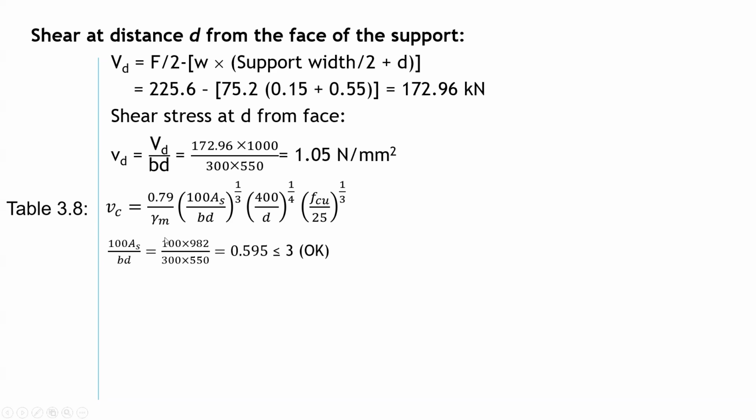In this case, for that beam, we have 2 bars only at the critical section, 2 bars of diameter 25. So the area will be 2 times 491, which will give us 982. So this value here is equivalent to 2 bars of diameter 25 millimeters, because we have 2 bars extended to the end or to the shear section, and 2 bars were shorter, so we only take the area of the tension steel bars at the shear critical section. So this is half of the area of the total steel at the midspan in this case.